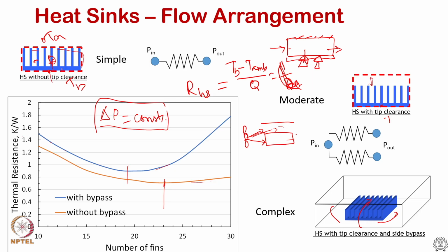what is required is that there are two parts to this: the convective heat transfer, that is the hA component, should be balanced by the m dot Cp component. m dot Cp is the sensible heat rise of air flowing through the medium. So, only if there is sufficient mass flow rate can it dissipate the Q that is coming from the surface area. So, hA and m dot Cp should be balanced in a heat sink design.